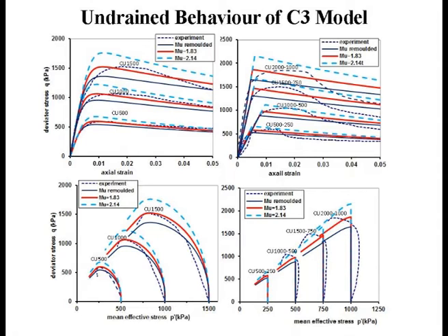In the sense that when you reach the peak, the soil starts to shear. And when it shears, the structure, the cementation, is lost even more quickly. And so as a result, it just comes straight down the critical state line. So the angle is the same, but you lose a lot of effective stress, because the soil is collapsing volumetrically, and so you generate a lot of excess pore water pressure, and so your effective stress is dropping. For the same angle of friction, the deviator stress is dropping.